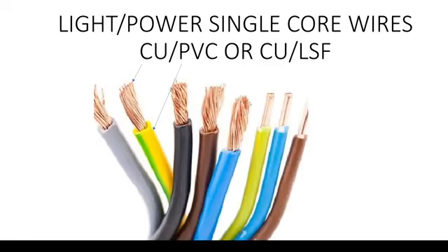So, single-core cables or wires are mainly used for small light and power circuits, as you can see in the picture. Their annotation goes as CU/PVC or CU/LSF.